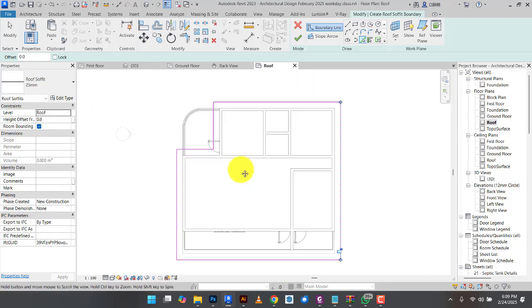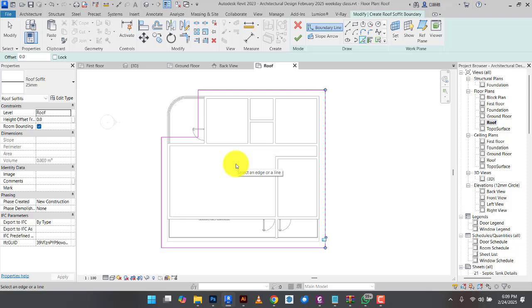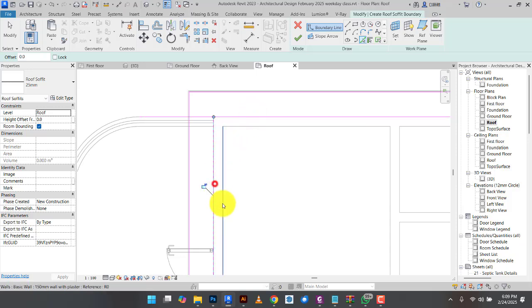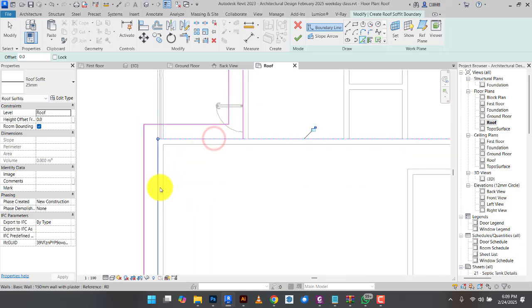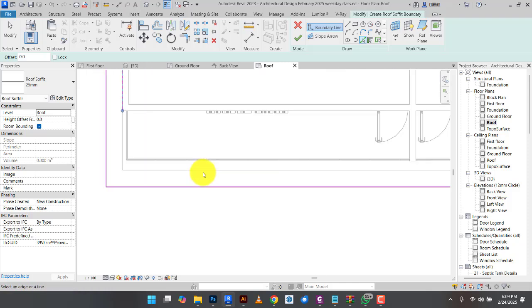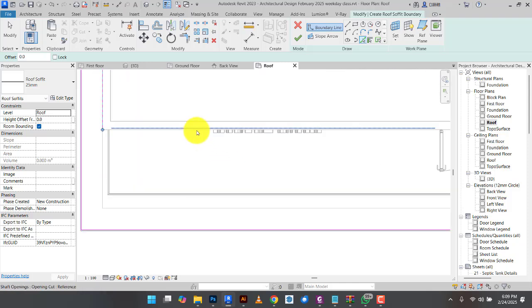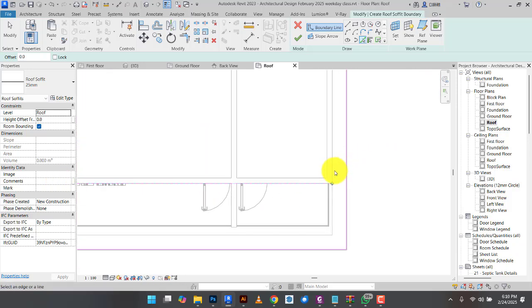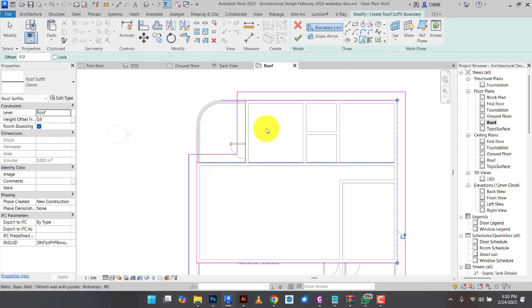That's all. Now, if I accept this, what it means is that the surface will pass through the whole building. Remember, we have to draw something in to create a void. So I still have to use pick line and pick the outside of the wall this way. Where's the wall here? You need to make sure your lines are not intersecting or overlapping.